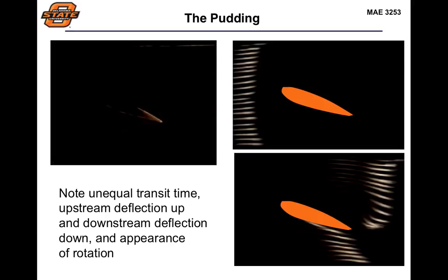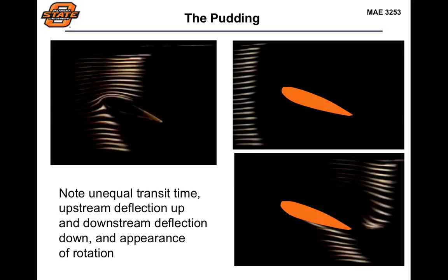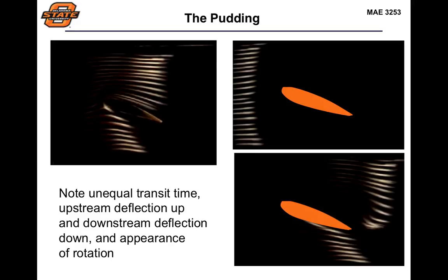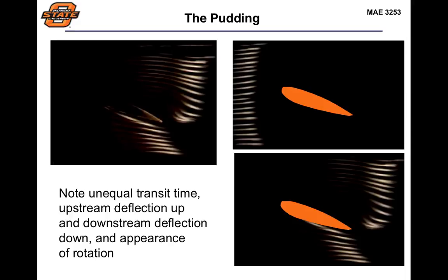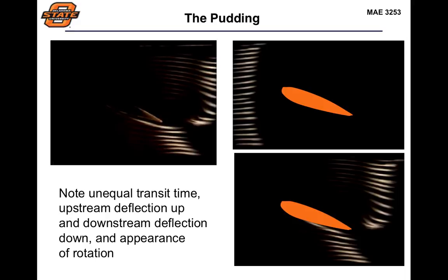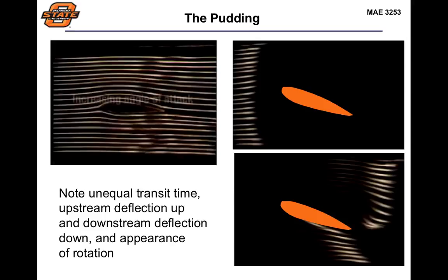So if we take these streamlines moving over the airfoil, which you'll notice are starting off all at the same location, as they're moving over the airfoil, that circulation moving around, in this case in a clockwise fashion, is moving the flow over the top of the airfoil faster than the flow over the bottom of the airfoil. And then you end up having these two sections leave at different times at that trailing edge location. And we'll come back and look at this video later when we look at other cases at higher angles of attack.